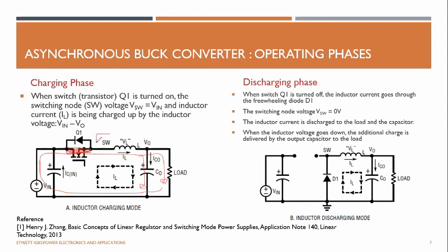We have this switching node, known as SW, which is very important when you're designing your controller, because the switch node is a very important thing for dealing with EMI, right? It's a very fast changing voltage point. When you turn on this switch, it short circuits this terminal. So if this voltage is V in, the switch node voltage becomes V in, because the voltage across a piece of wire is 0. So the switch node voltage becomes V in, the supply voltage.